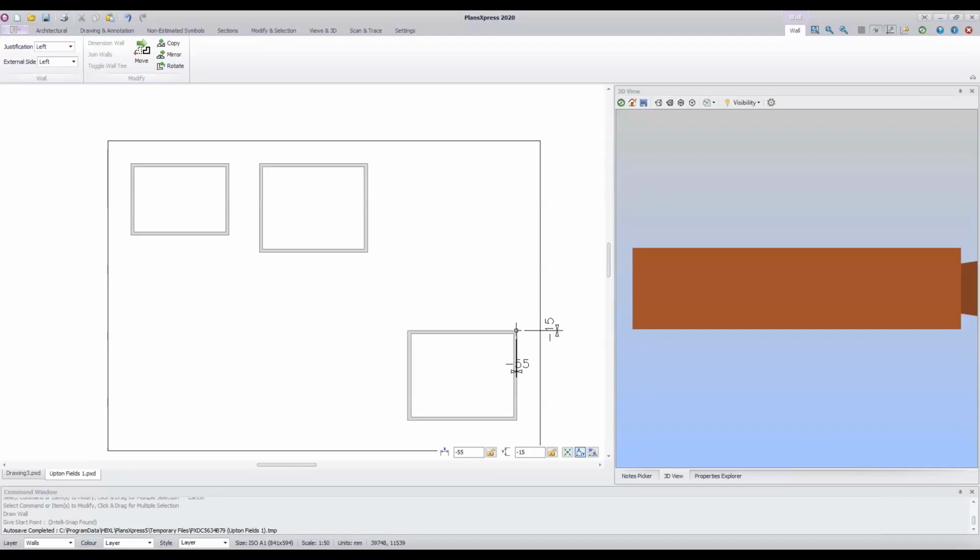When you press the R key, you'll see these dimensions appear. The dimensions are telling us the position of the cursor relative to that endpoint that we hovered the cursor over. So it's linking the endpoint with your cursor. So you could just do it by eye. You could say I want the garage to be 6 meters back and 2 meters across. You could do it by eye.